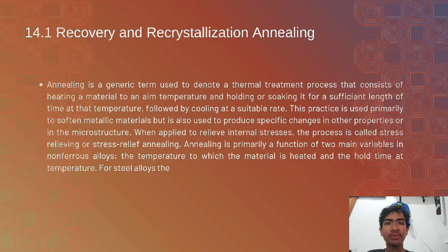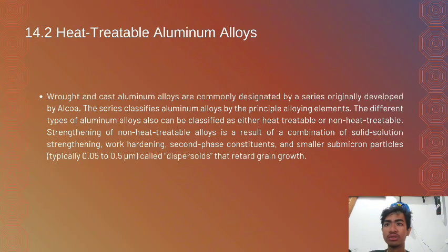There is some movement and readjustment of dislocations during the recovery stage, so some properties do change during recovery annealing. For example, the electrical resistivity of an alloy is typically increased by cold working, but can be recovered before annealing has a significant effect on hardness.